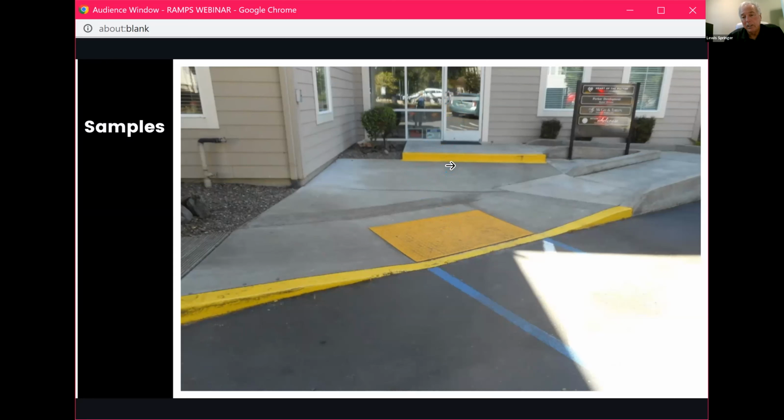And then this is actually a flare sloping at 1 to 10, and then coming up to the pedestrian walkway that's accessible to the front door. It all slopes less than 5, so it's not a ramp. But this as the accessible route can't come down and hit a 1 to 10 slope and then down to the landing. This should have been a parallel curb ramp on both sides.